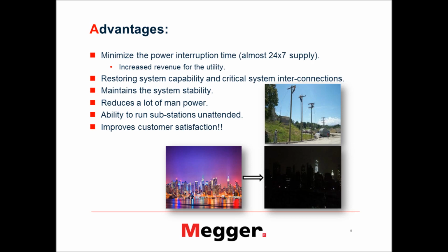So if you don't have an auto closing mechanism, there has to be a person who closes that specific circuit breaker. That will again lead to longer interruption times, making your indexes that we discussed in the previous slides worse, and it causes a lot more problems.